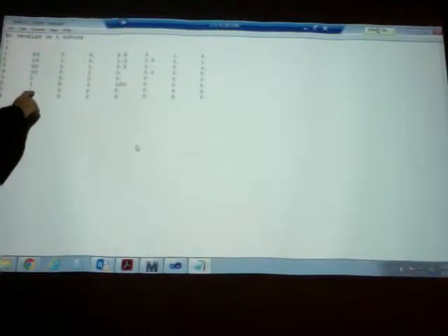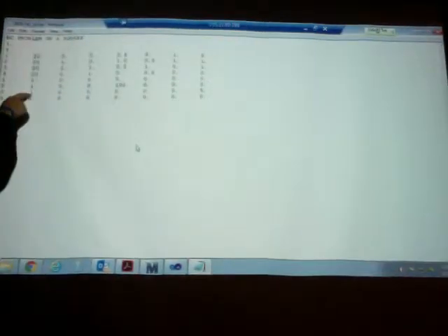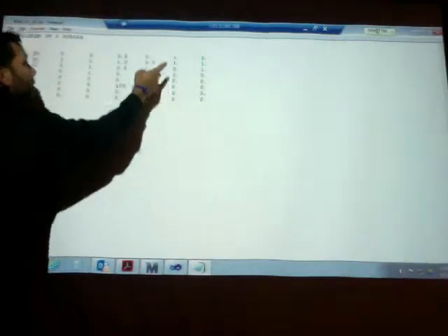That is the exact same problem we solved with MathCAD, and we want to see if we can replicate the same solution. Temperature is equal to 0 on the top surface, and heat flux is equal to 0 on the left surface. Is that clear? That's all you need to solve a problem.